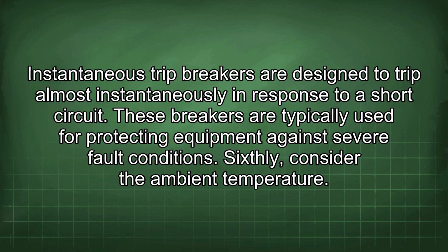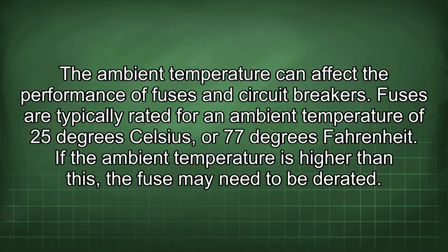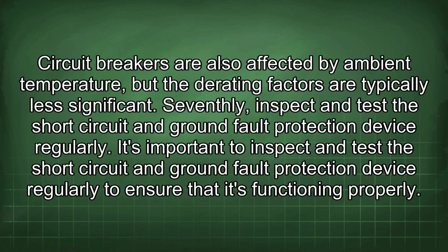Sixthly, consider the ambient temperature. The ambient temperature can affect the performance of fuses and circuit breakers. Fuses are typically rated for an ambient temperature of 25 degrees Celsius or 77 degrees Fahrenheit. If the ambient temperature is higher than this, the fuse may need to be derated. Circuit breakers are also affected by ambient temperature, but the derating factors are typically less significant.